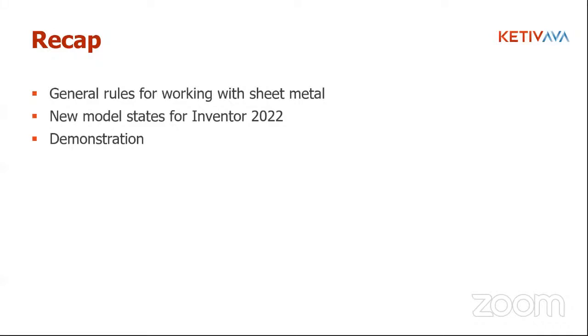We went over knowing your manufacturing process and your tools and their capabilities when designing a part, before you start designing, preferably, so you have a timely, productive design. You don't want to put too many bends in a part, not knowing what tools you have. You may not be able to make those bends, which has happened before.